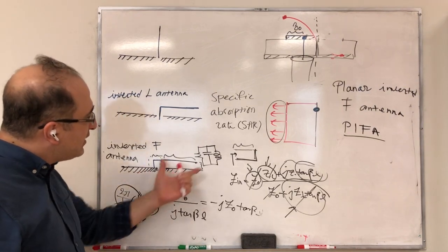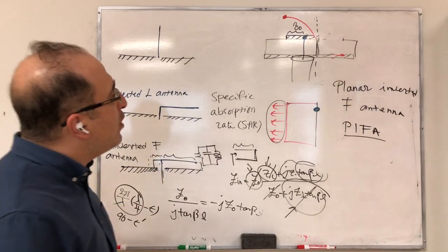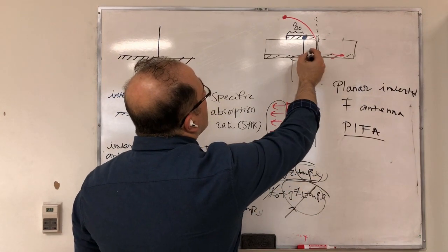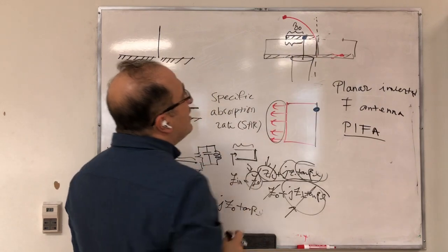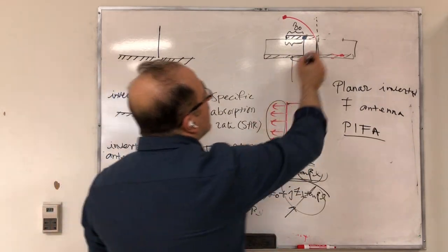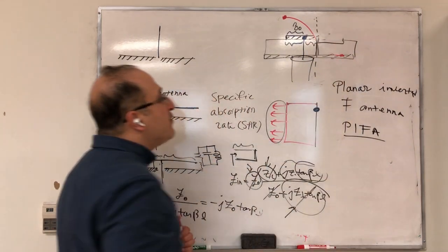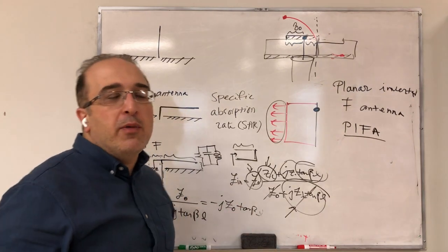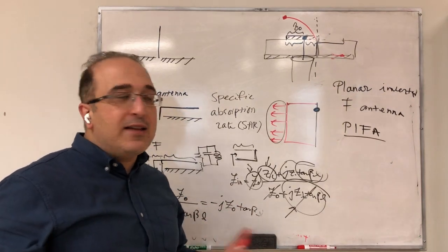Similar to this style, you could also discuss a circuit model here by saying that, for example, in a patch, you can consider this as one length of transmission line. If this was a full patch, you can consider that as a different size of transmission line, and so on, and understand it from a circuit viewpoint. This simplification could help you understand the system better.